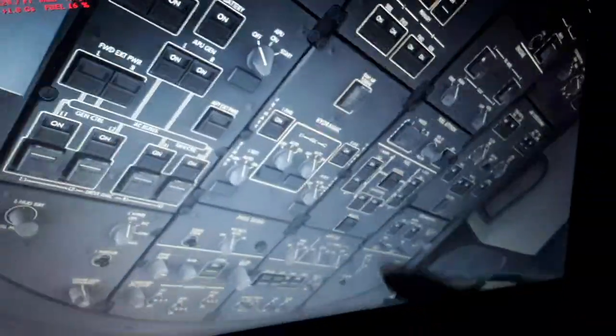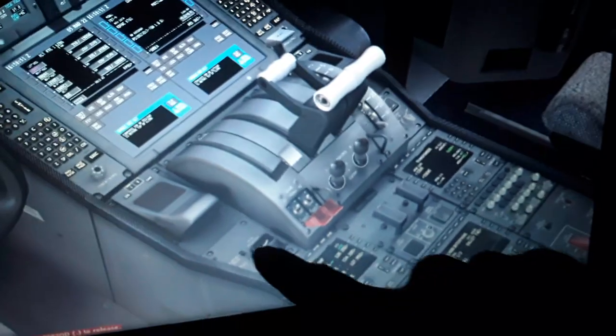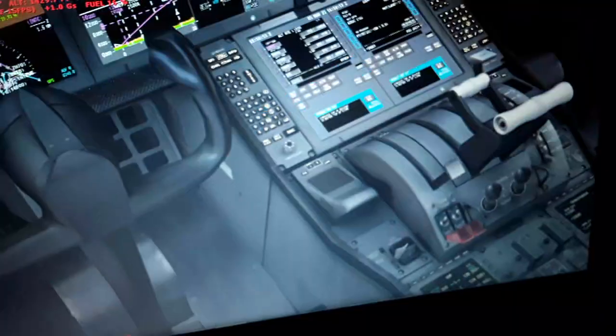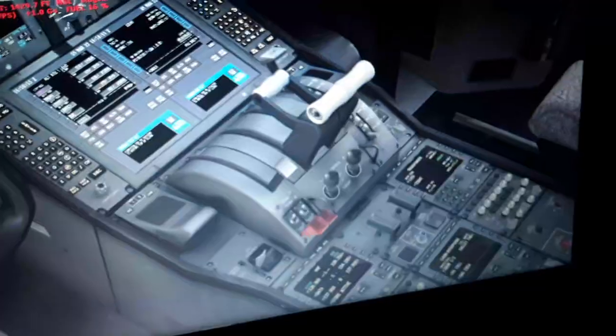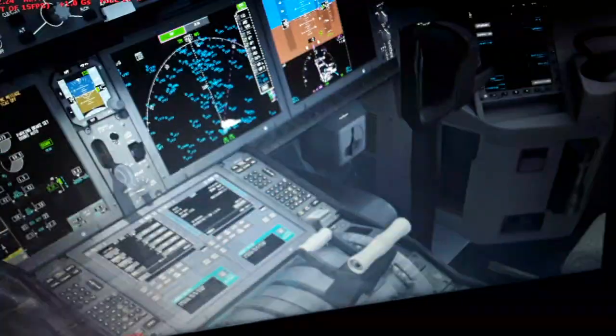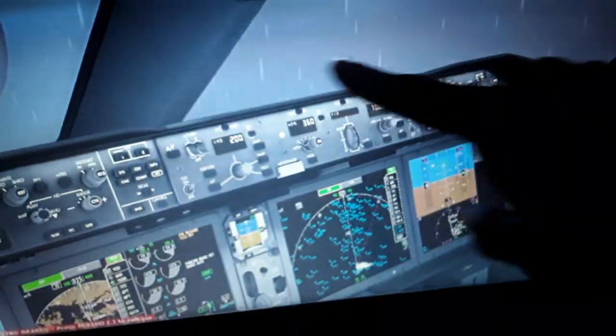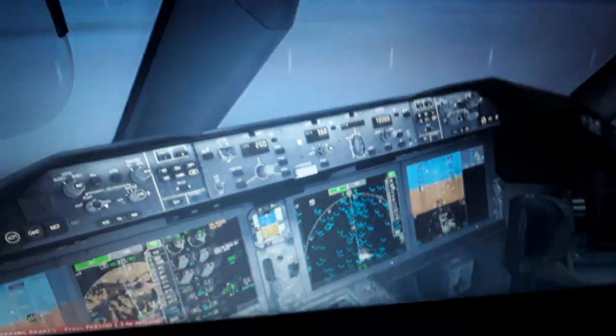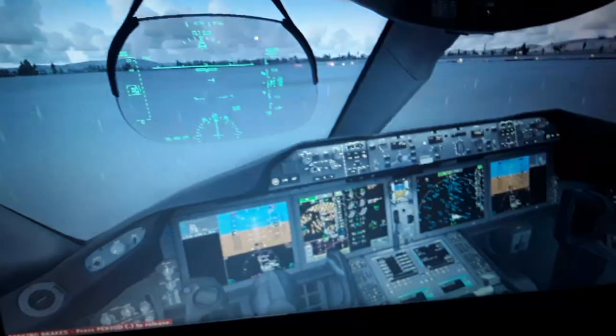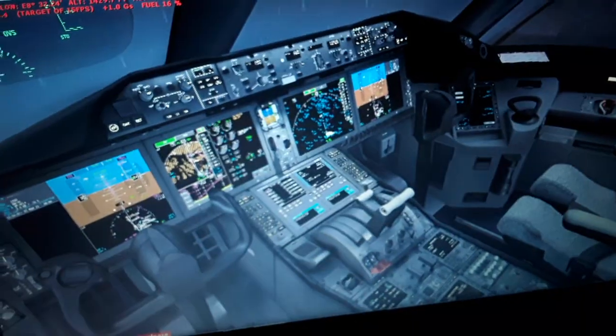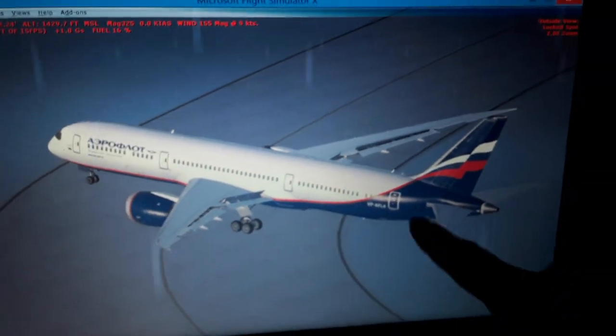So if we're gonna lose the hydraulic systems here, the L2 or R2, we're gonna use the alternate pitch trim, maybe, and the manual only, and we're gonna have to use the cutoff position for that. We're gonna disconnect the autopilot and the auto throttle from the auto trim function. So you're gonna have only manual trim for this horizontal tail over here, as I told you.